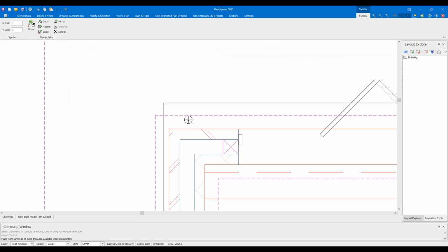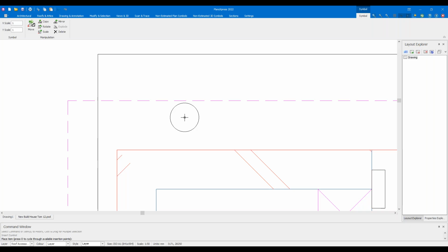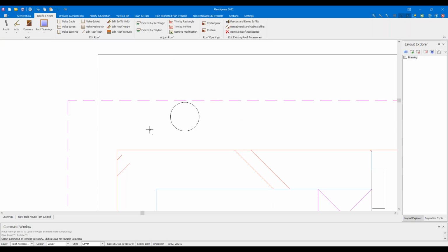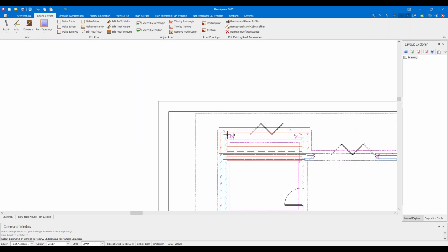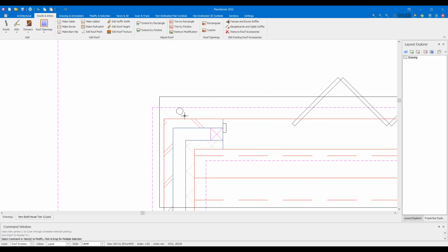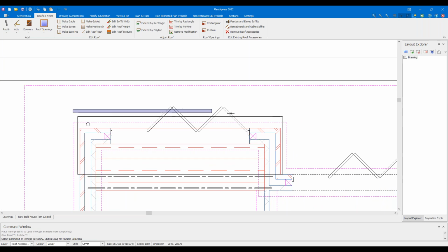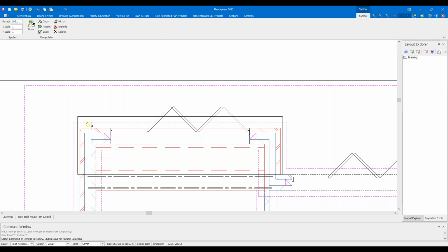Now this being a circular symbol, when you place it, it looks like it's placed, but it wants to rotate to know which way it's facing. You have the line to indicate a little turret. So we just need to click somewhere. Because it's a symbol, it just behaves each time. And now we've got our guttering finished. So the length of guttering itself is going to be associated with the length of the roof. That's always going to be part of that. But the actual downpipe and outlet and stop ends is calculated by that one little symbol.